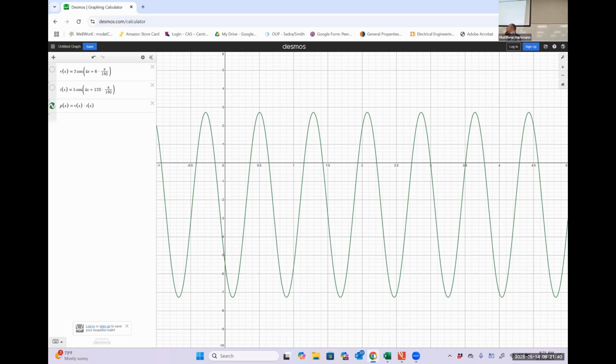Exactly right. Since we calculated everything from an absorbed power perspective, since our average power is negative, that means that on average, our load is actually supplying power to our source, okay? Anytime we see the value of the instantaneous power being positive here, that means our load is absorbing some amount of positive power. Anytime it's below the horizontal axis, or negative, that means our load is actually supplying power, okay? So it's sending power back to the source.